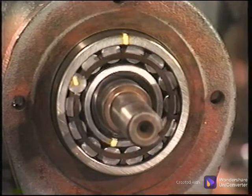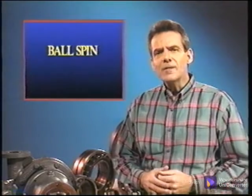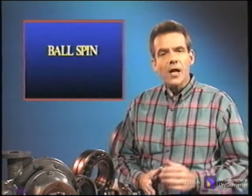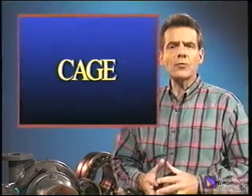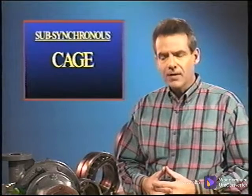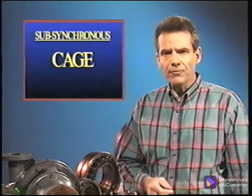1, 2, and a fraction. This roller defect frequency, or ball spin frequency as it is commonly called, is also non-synchronous energy. In our approximations, we've shown that the ball spin frequency, the outer race frequency, and the inner race frequency are all non-synchronous energy. The cage frequency is subsynchronous energy. That is, it rotates less than 1 time per shaft revolution. Therefore, a subsynchronous frequency is a lower frequency than shaft turning speed and is a fractional order value.